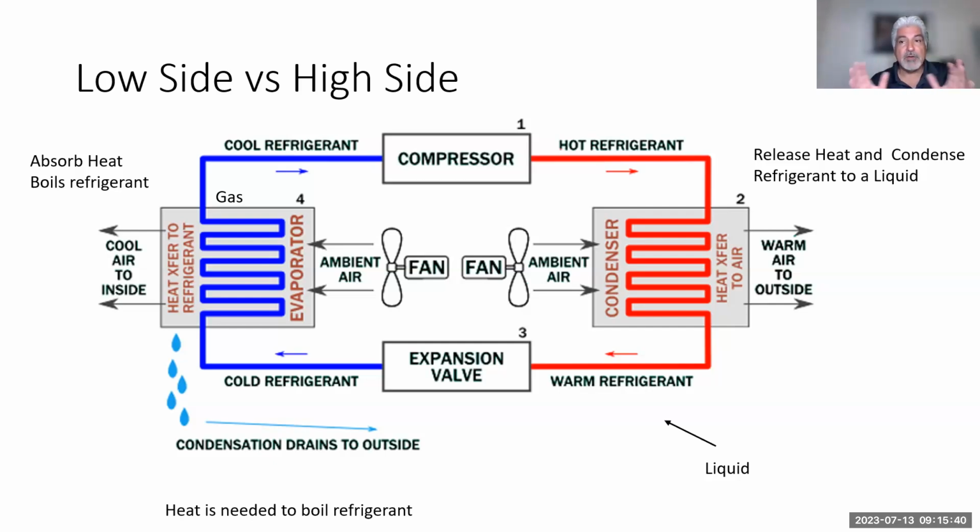So when you look at the vehicle compartment, you're in recirculation mode, recirculating about 90% of that air inside of the vehicle compartment or that truck compartment. That means that heat is actually being carried by that refrigerant, and it gives it up at the condenser. So as much as you feel cold air in your face when that air conditioner is working properly, you've got to understand that we're also taking that heat. What happens to the refrigerant in the evaporator is that it actually turns into a gas. The proper charging and the proper oiling make this happen.